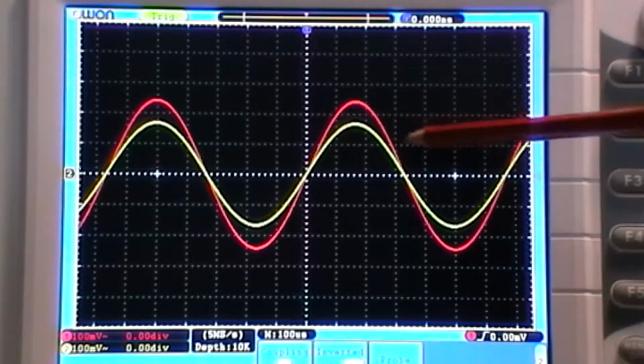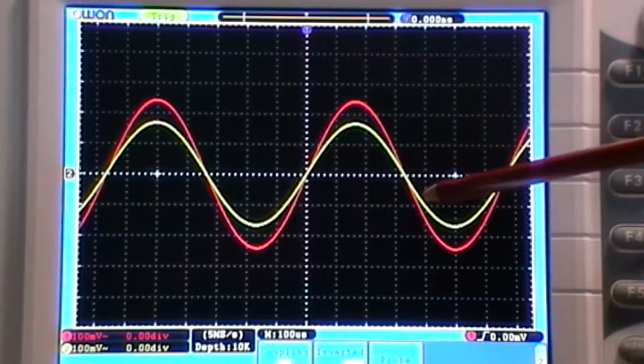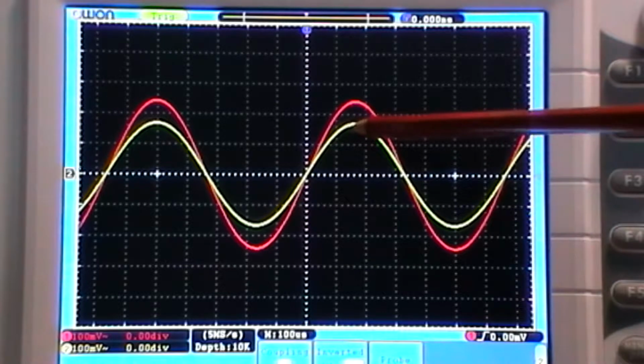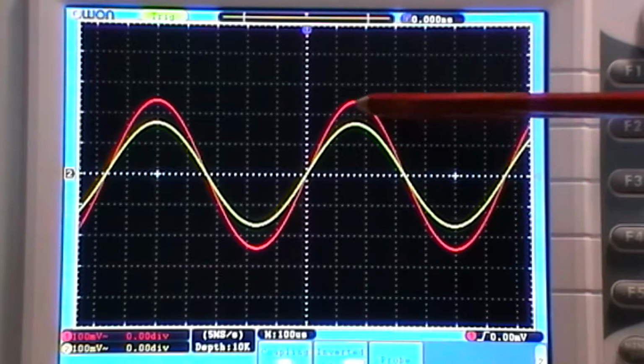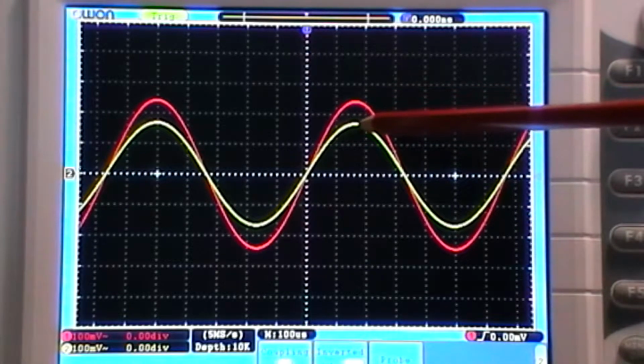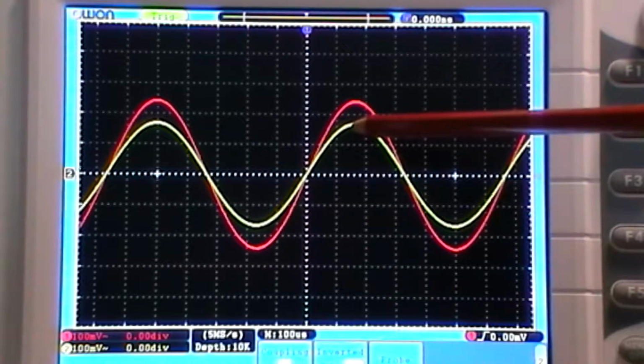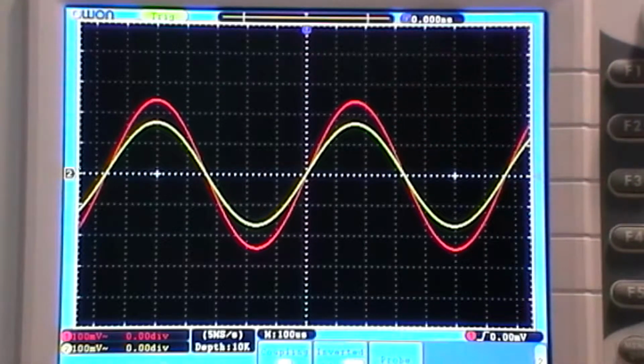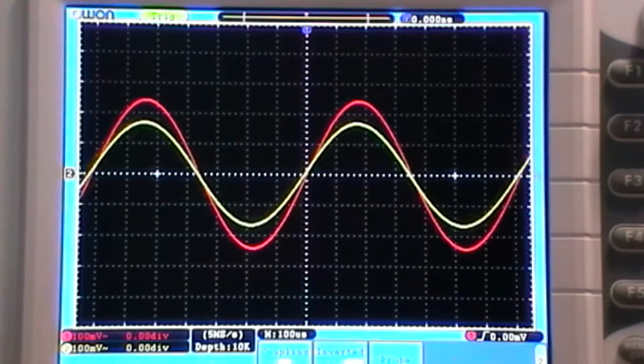We've got no phase shift, so we're in pretty much the middle of that frequency range, but we're always going to be slightly less than the input frequency. And then as I get lower below my cutoff point, the high pass filter is going to attenuate this, and as I get higher and get a higher frequency, my low pass filter is then going to attenuate this signal above its cutoff point. So if I now take this frequency down